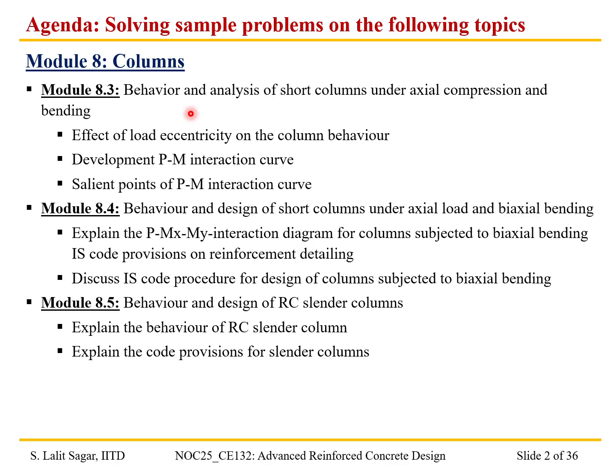We also developed the PM interaction curve, for a column subjected to simultaneous axial and bending loads. What does the PM interaction curve look like, what are its salient points, and how do we construct it for any given column cross section?